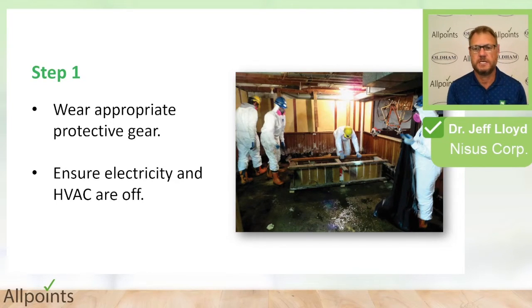You're going to be potentially working with a lot of sewage contamination, with a lot of mold spores, etc. So appropriate personal protective equipment is absolutely necessary. Even though you're not applying any protective chemicals yet, you still want to wear the appropriate personal protective equipment. And make sure the electricity and the HVAC are off.